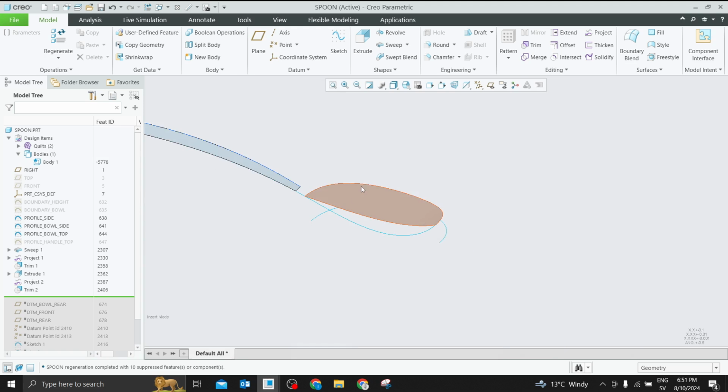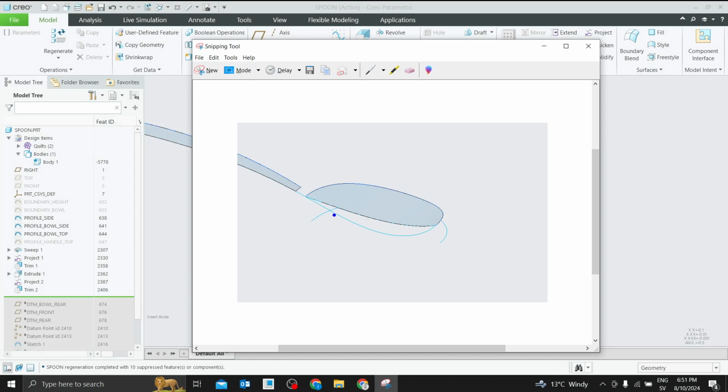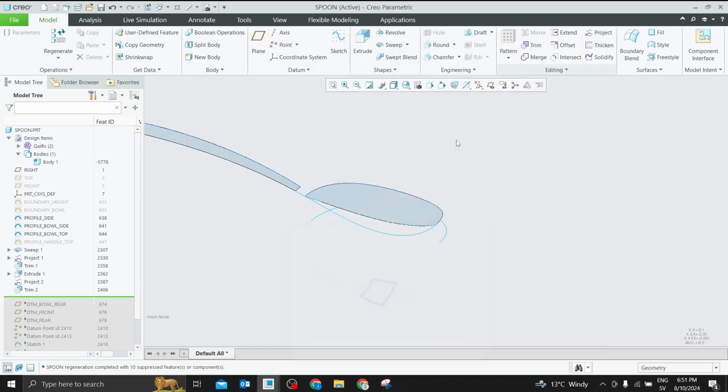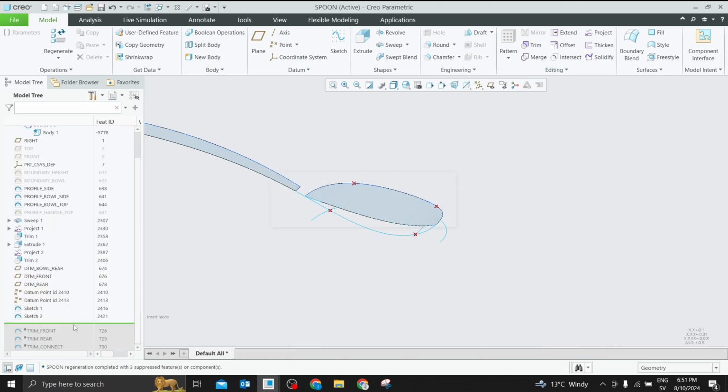Then a curve. If I take this direction here, a curve from this curve goes up like that, and another one goes up like that. Hence, I can now easily create this surface, the middle section surface. In surface modeling, we have to create segments of surfaces, then merge them together. Those are the planes I'm talking about, and those are the sketches I'm talking about there. And this one here, I don't need it.